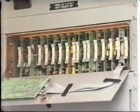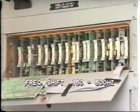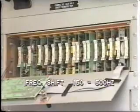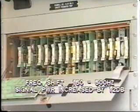Where the signals are transmitted by an audio tone system, the operation is similar. The shift in frequency is within the range of 150 to 500 hertz, and the signal power is increased by 12 dB. All of these schemes that we have looked at so far are directional comparison schemes. They compare the direction of current flow at each end of the line by the use of directional relays.